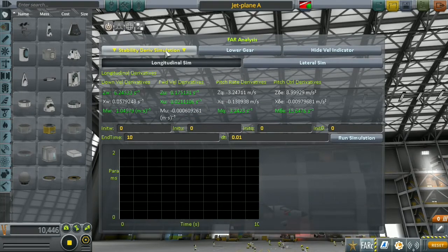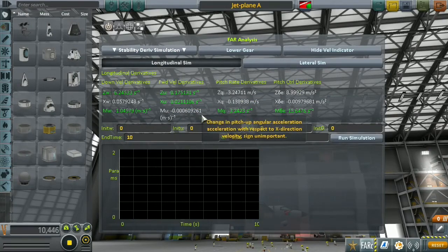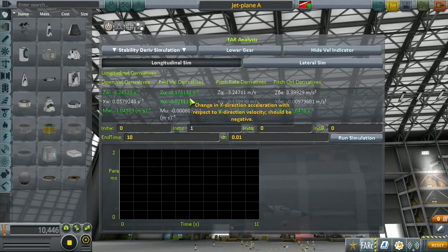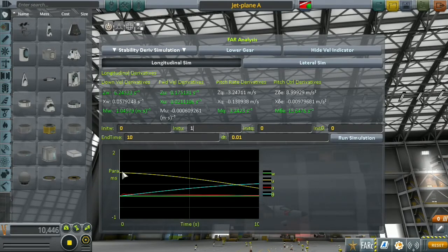The page 3 numbers have been copied to this block of numbers. And here we can see what actually happens if all of a sudden the aircraft is flying 1 meter per second faster than the equilibrium. What happens is that the speed, this u, will start at this +1, that's 1 above the equilibrium, and then it will tend back towards equilibrium.